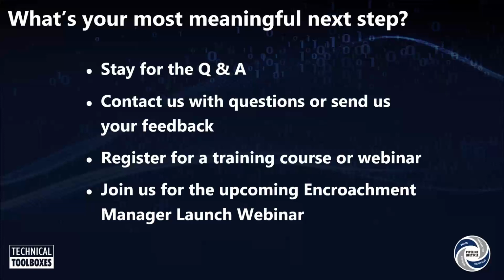Now with that, Joe, let's go back to corrosion for a second. Someone picked up on that potentially RSTRENG plus can assess more than one effective area. Is that the case, Joe? Yes. One of the things that we recognized years ago, when I was still working in the field, was that when they put RSTRENG together, the maximum length of corrosion we were seeing, back in the late 90s, was probably 18, maybe 20 inches long. Since then the corrosion lengths have begun to get much longer. In fact, I've seen them from joint to joint.